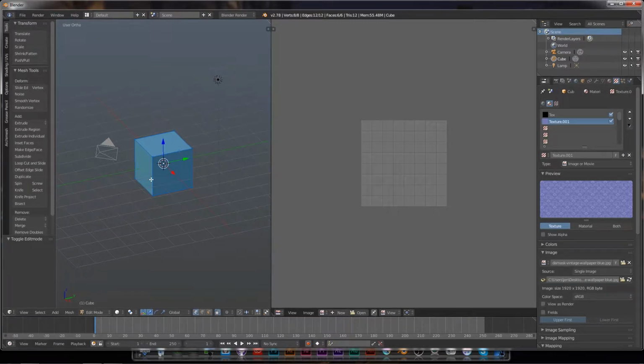We need to make seams on the cube so we can unwrap the cube onto the UV map. Use the shortcut Control-Tab and make sure that you are in edge mode. We need to choose the top front edge and the C-shaped edges on the two sides using Shift right click.